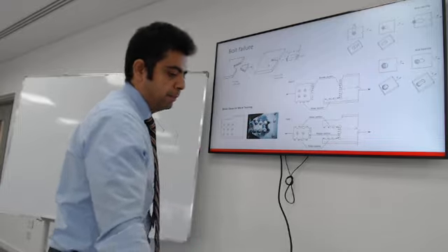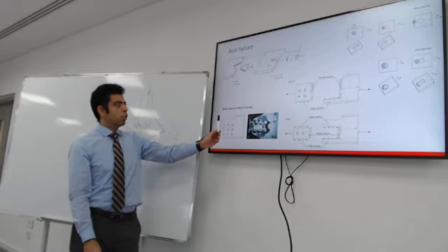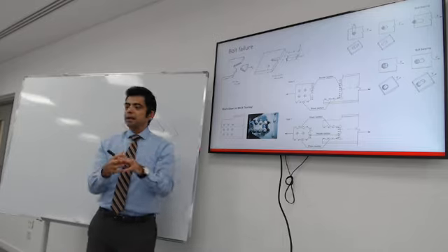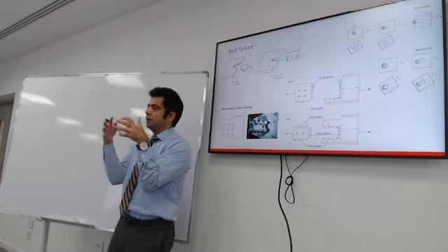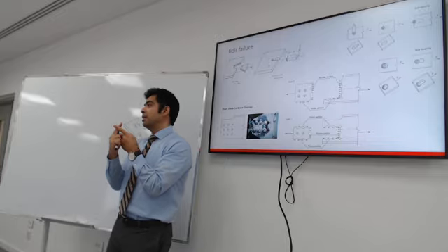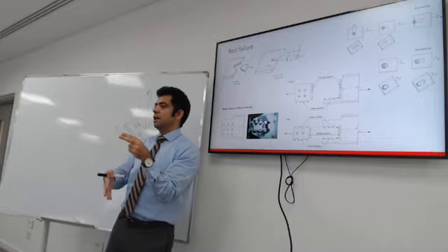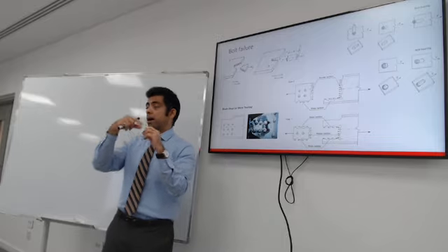This is another check. The shear block, or block tearing, is that if you have a group of bolts tight up together, the connection could fail not only in the bolt or at a cross section, it could be the boundary of the group. It could be the boundary of the block.